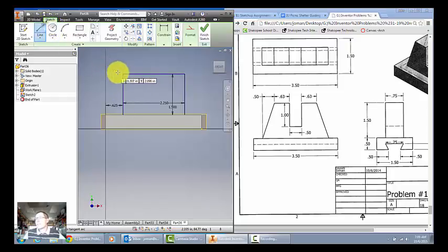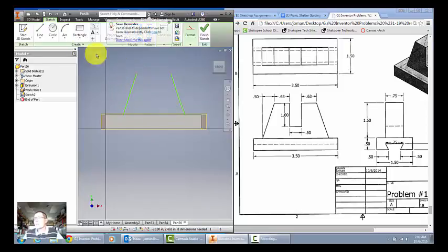Okay, we'll start cutting away at this thing. From this corner, I'll go in 1/2 inch. I'll come back down. I'll do the same thing over here, 0.5. Come back down. Do some trimming. If things won't trim for you, you'll have to select them and hit the delete button instead. They have to cross something in order for that to work. Okay, so now we have our angles taken care of without actually typing any angles.